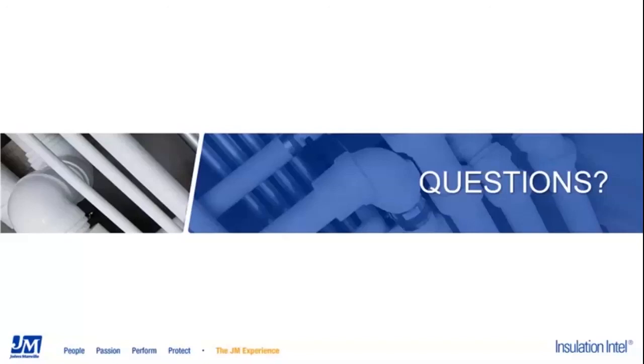Additional specifications. Well, first of all, I would be curious to know a little bit more about the application, because what catches my ear right now is 180 degrees Fahrenheit. So if this is the service temperature of the piping, let's say, or a tank, then obviously some insulation will need to go over the piping or the tank, because from the Zeston perspective, it should be used at temperatures between 0 and 150 degrees Fahrenheit. So we would need to specify some sort of insulation if that's the case.